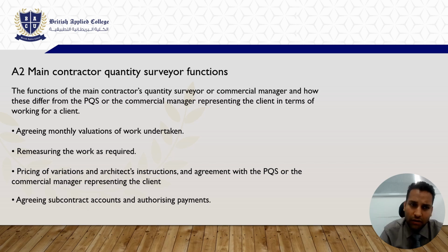Remeasuring the work as required is also one of the basic duties of the quantity surveyor, because all the work measurements are done by the quantity surveyor of the client. When the contractor gets a project, he will send his quantity surveyor to reevaluate that whatever is proposed in the document is exactly the same on site, so that there are no variations which would lead to losses of funds and delay in time.